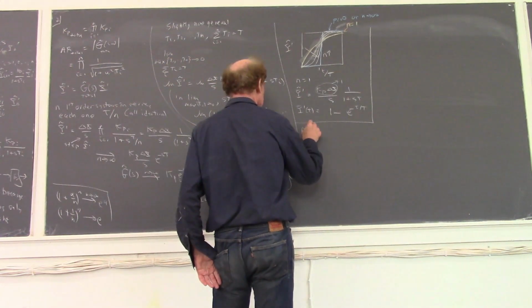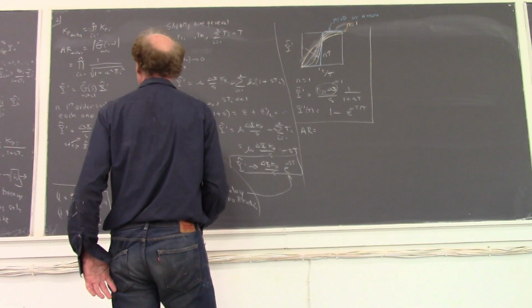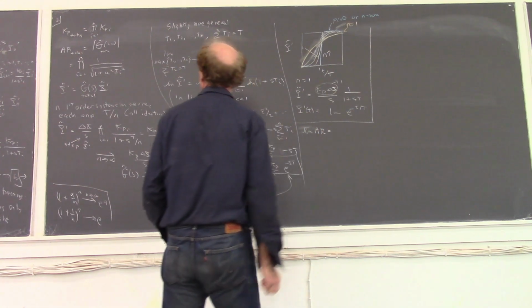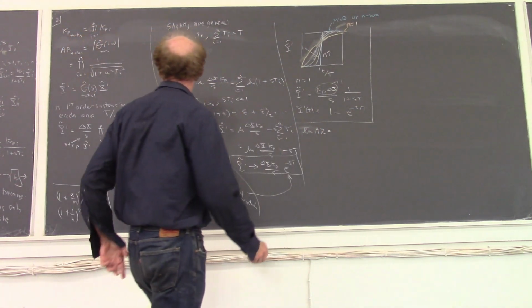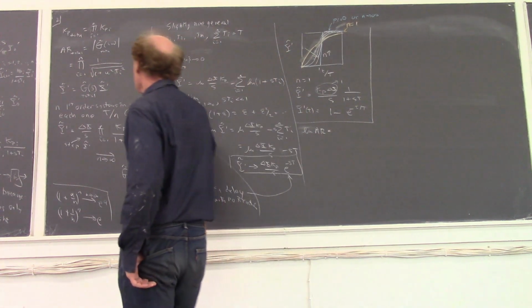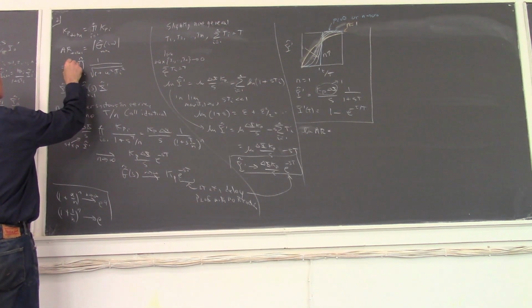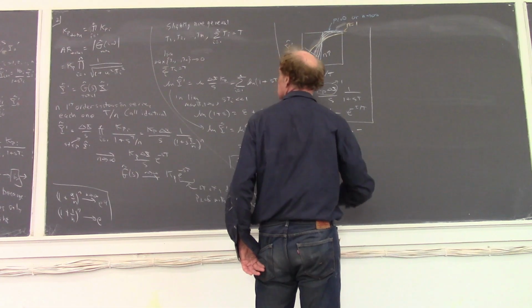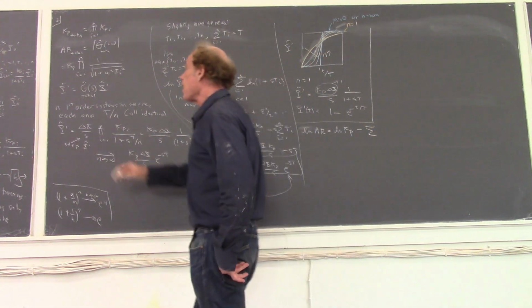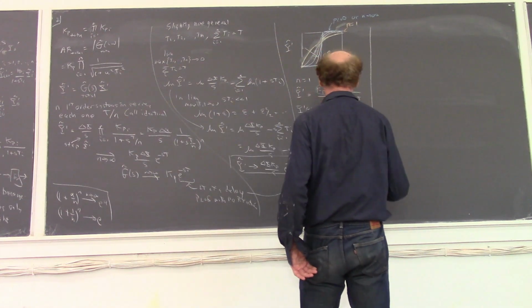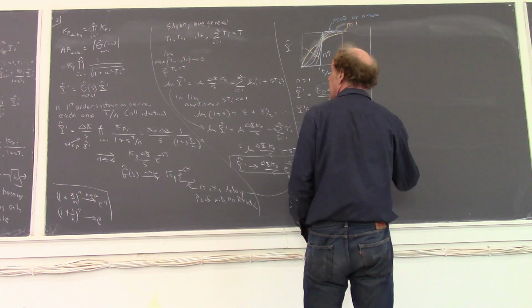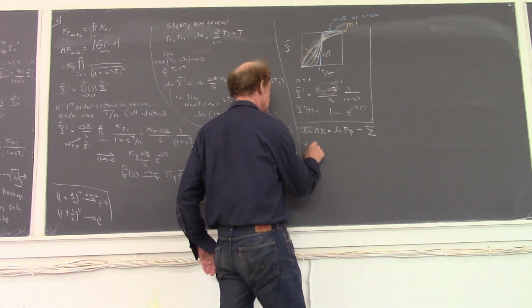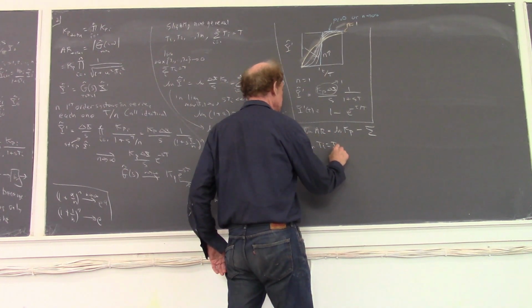Okay, so let's look at the amplitude ratio as n goes to infinity. So let's look at the log of the amplitude ratio. And that's equal to the log of this, which is the sum. So here I actually left out the Kp. So it's the log of Kp minus the sum, because the product becomes the sum. And it's minus because it's in the denominator. And here I'm going to look at a case where tau i, Ti is big T over n.